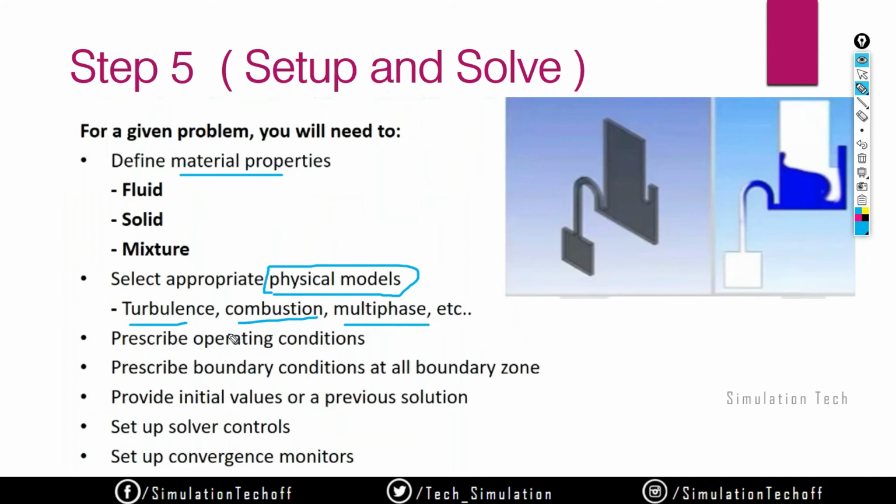So what type of turbulence happens, whether it is laminar or something else like k-epsilon, we have varieties of turbulent flow. You need to define the turbulence of the liquid. And the operating conditions: what is the initial temperature, what will be the changes in that condition, pressure, inlet velocity, everything will be given in the operating conditions.